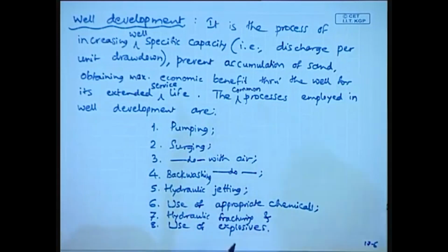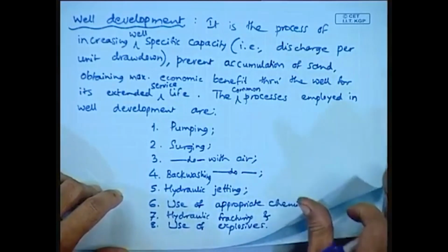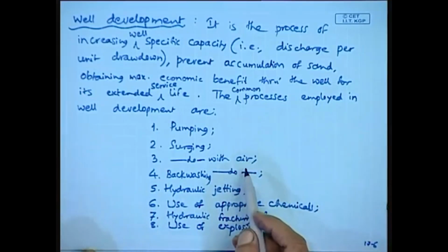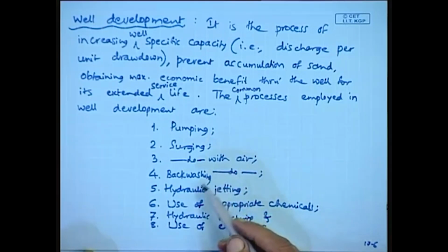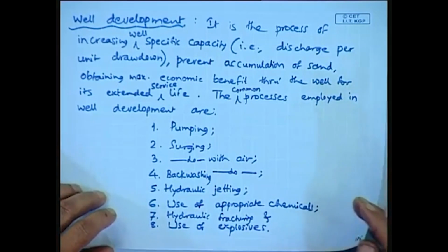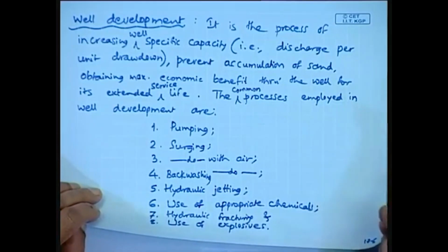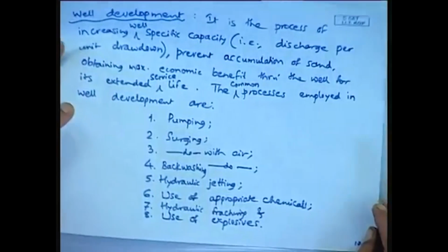And here I would like to bring to the notice that this compressed air wash is very effective in removing the fine clogged particles, and therefore we can maintain a high level of specific capacity, or further increase the specific capacity.